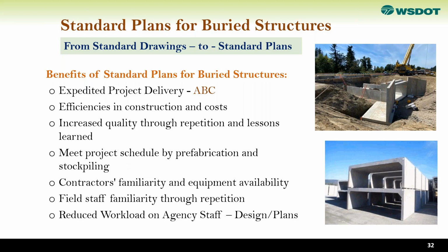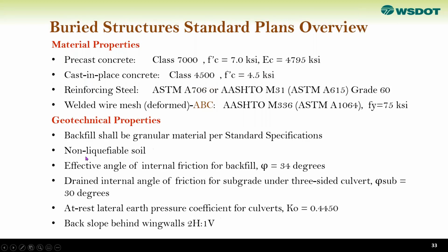The contractor could go to fabrication, stockpiling, and when the time is right, come to the job site, dig the stream and put the segments together. There is also contractor familiarity and equipment availability because of repetition, field staff familiarity through repetition, and reduced work on the agency load, because all the work that we do in-house or by consultant to prepare the design will be covered in the standard plans. That's a big help for us to do other projects.